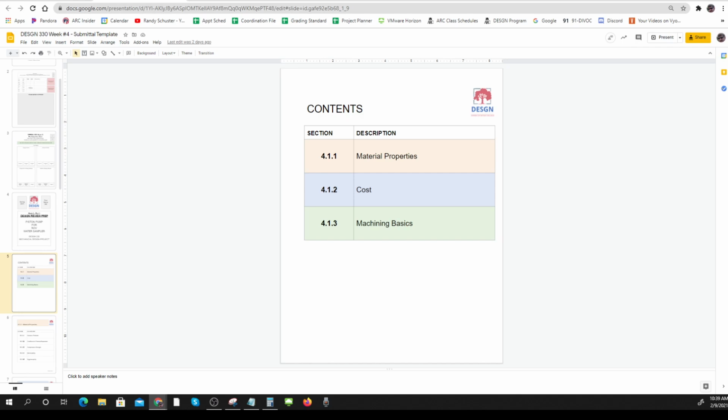And your job is to factor that in. If there's a huge need, we're going to design this for that. I know we'll spend money on prototypes, but I'm going to make 10,000 of these. Well, now your injection molding will cost you $30,000, so it'll be $3 per part that you make. So you'll be able to do some of that thinking.